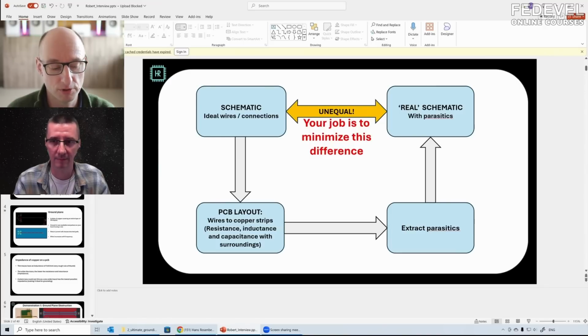And another thing is something I call self-interference. So let's assume you have a board with a very sensitive analog channel, like a microphone. And a few centimeters further, you have a digital processor that's running at a few hundred megahertz. And I think, okay, those two frequencies are really far apart, so they're not going to hurt each other. However, if you put a signal from a few hundred megahertz into an analog front end, it is going to demodulate it. There's no way you're going to stop that. And this way, you still get something they call audio breakthrough, and it limits your dynamic range.